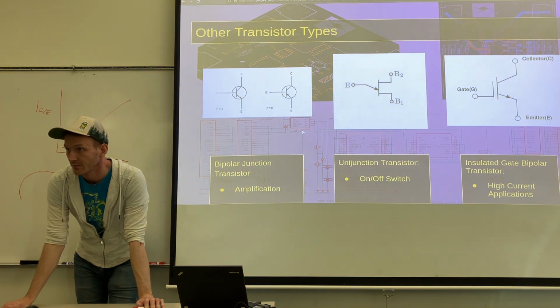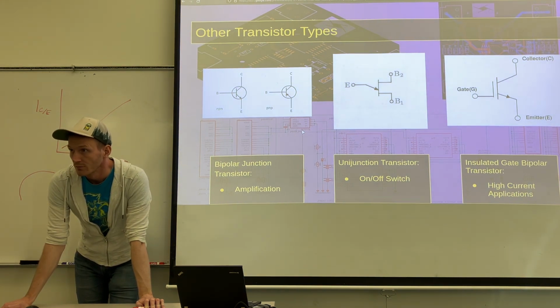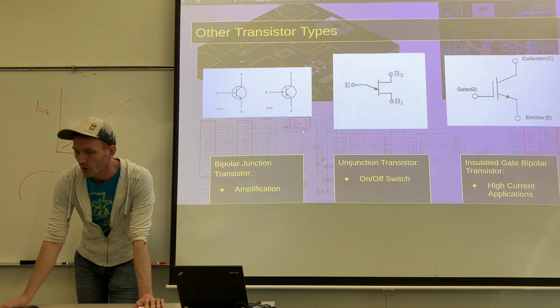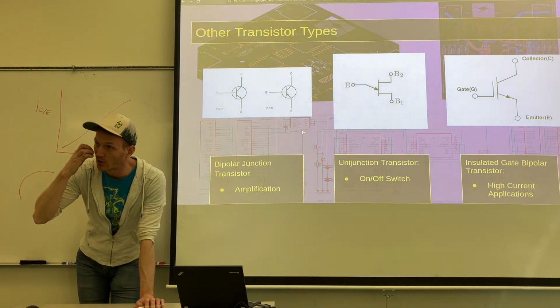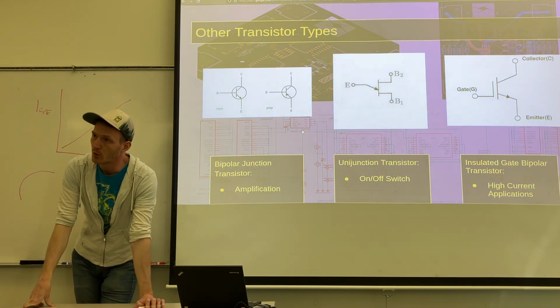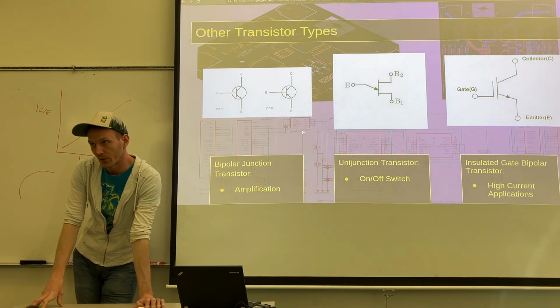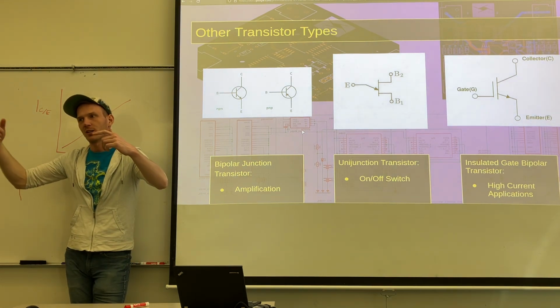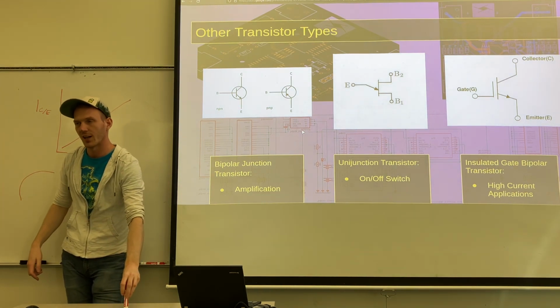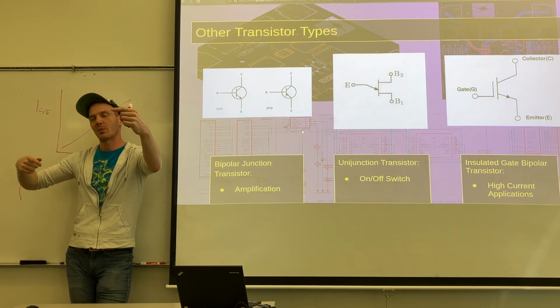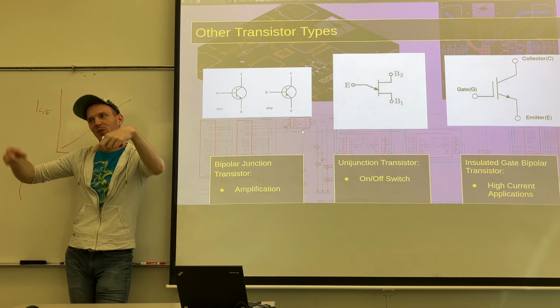What would 1,000 amps even look like? I can't even. Well, for example, on some of the United States Los Angeles and Ohio class submarines, they have a giant battery and they have a giant AC distribution system. In order to convert power between the AC and DC systems, for older ones, they literally have a giant DC motor connected to a giant DC generator. So you use a DC motor to make an AC generator, but they're wired up so that they can also be an AC motor to a DC generator.